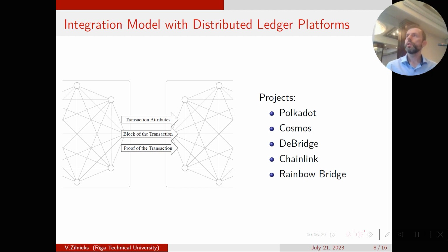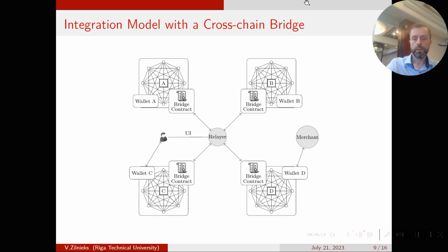So, in this way, we can calculate the instantaneous electric load, and also, by integrating, average monthly values of heating demand and electricity consumption. So in this way, the seasonal COP turns out to be 3.75 and 4.0 for linear climatic regulation and parabolic climatic regulation respectively. So we have a reduction of consumption of about 9%.